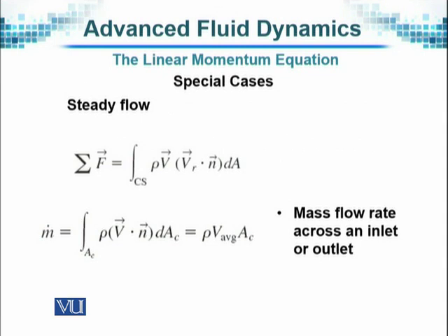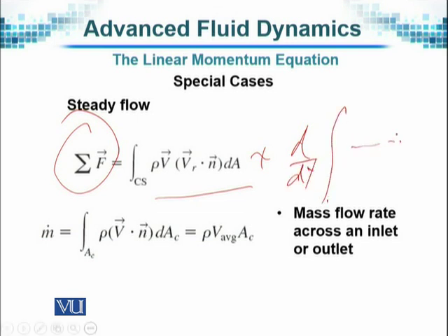As a special case of this, if the flow is steady, then obviously what will happen? Earlier, when we were writing the total forces, there was this force plus d by dt of the integral of similarly another term. But that term turns out to be 0 because the flow is steady, so there is no contribution with respect to change in time.